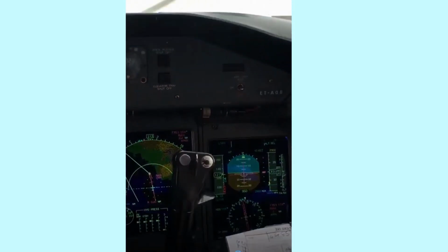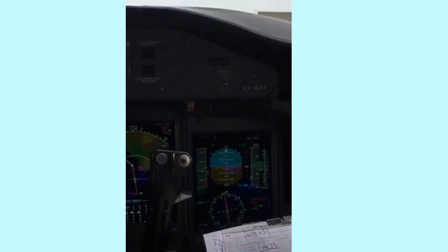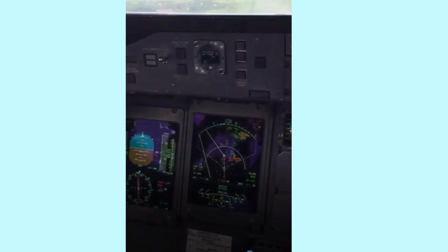And now I just want to pause here. I'm hoping you'll be able to see. If you see there's indication which is AP here, this is on the first officer side, the same on the captain's side, my side as well. It says autopilot. Can you see autopilot here? So with autopilot you can see that the speed is just around Vref. So that's perfectly okay with autopilot. So the autopilot is saying that for us to maintain the Vref, we have to apply a torque of just around 27%. And the same thing here on my side as well.